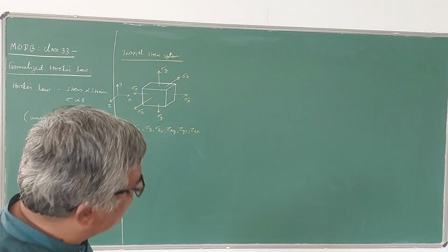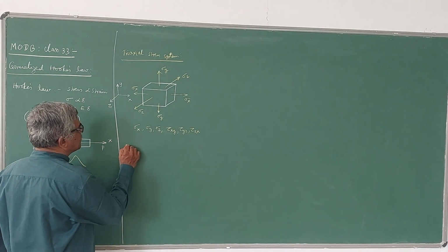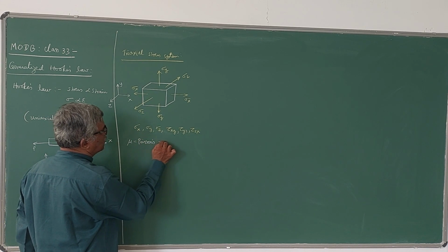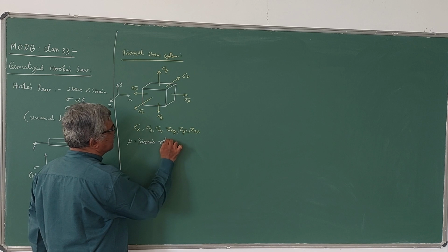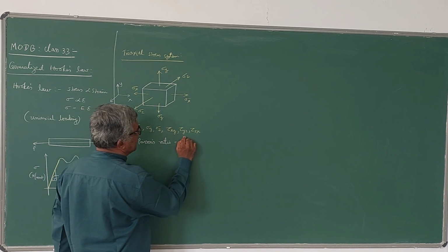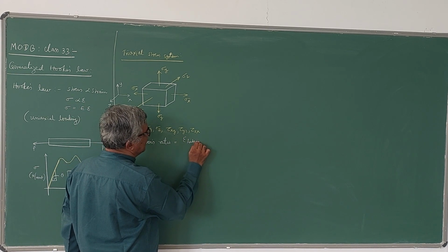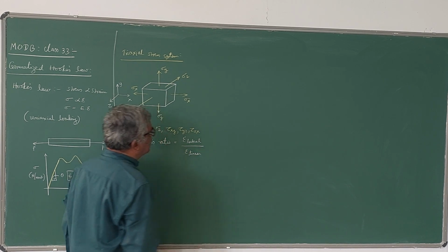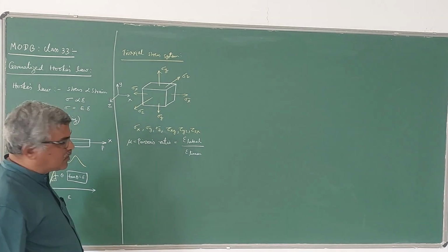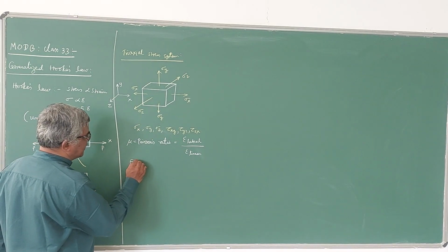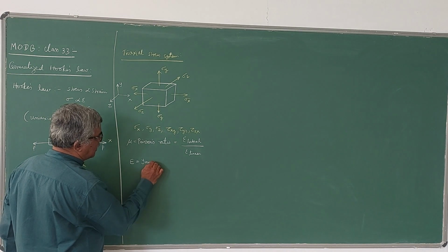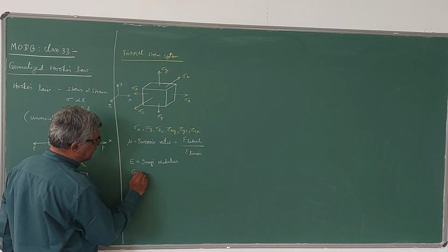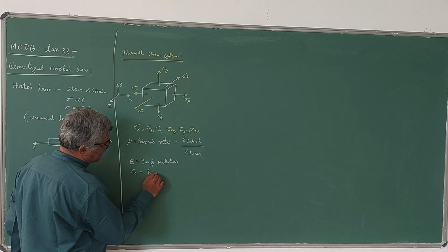So you have learnt in strength of materials that if mu is the Poisson's ratio, you know that Poisson's ratio is the ratio of lateral strain to linear strain. Within elastic limits, once again, it is a constant. So just like Young's modulus, this is also an elastic constant. So E is the Young's modulus, and you have one more called rigidity modulus, G, or shear modulus.